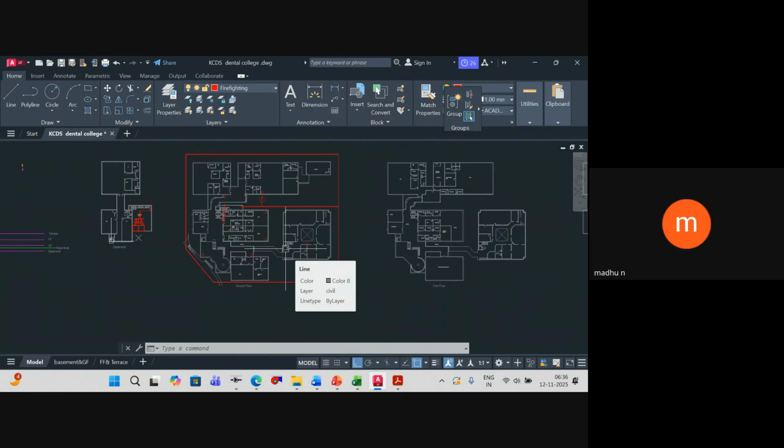No, because this is the minimum number of zones. I can have more number of zones also, right? Yeah. But it's only adding to your cost. I mean with 3 zones we can manage, right? You can manage, but there are two ways of looking at cost. If you don't split it, what will happen? Your horizontal pipe length will increase. I mean, your main pipe sizes and all will also change.